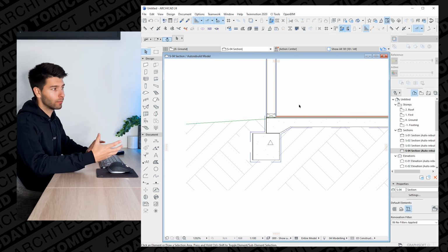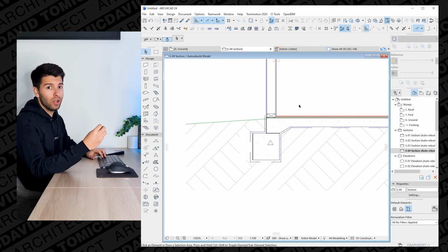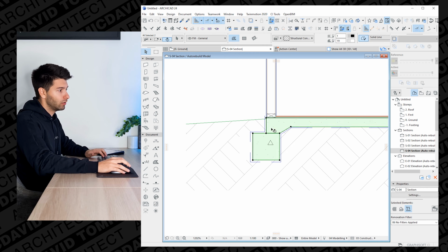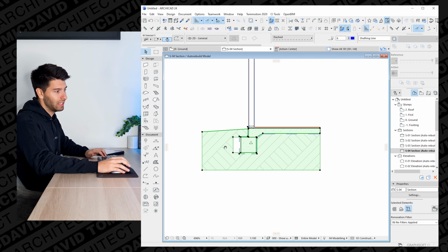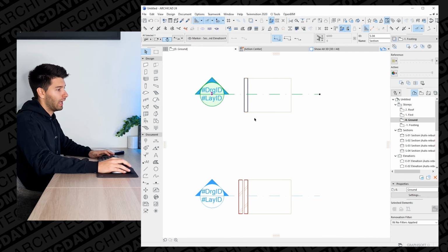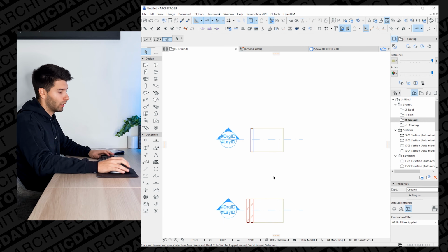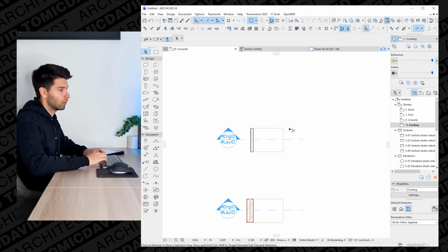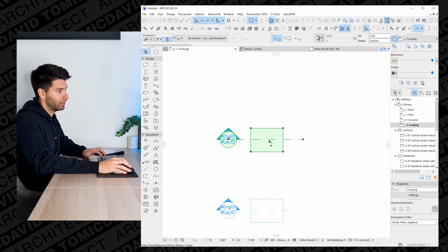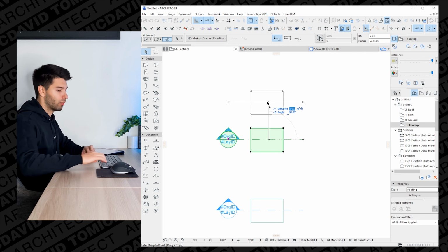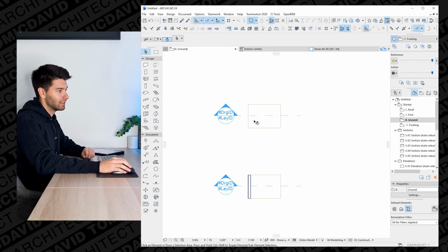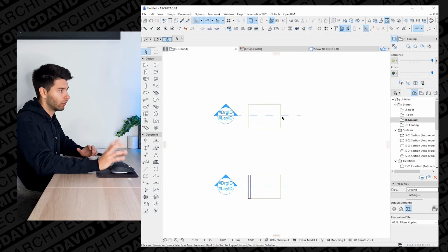So section 2 is now completed, and we're going to move on to our concrete tilt-up wall sitting on a concrete slab. So what I'll do is, once again, I'll simply copy these so I don't have to redraw them. Control C, close that, and move across to our next one. Now, to simply move the process along quicker, I'll go Control down arrow, select both of these, Control D, Control holding Shift, pressing D, moving 3 meters up, so that we have our slab created and we have our sectional marker created as well.